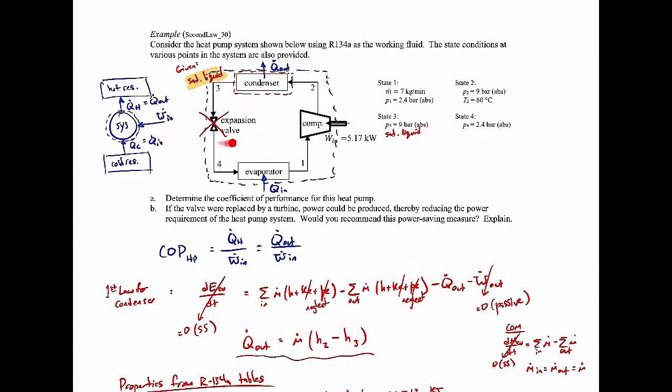That's in fact why these heat pump cycles and refrigeration cycles use expansion valves rather than a turbine, because you just don't get much out of the turbines. So you might as well go with something much simpler and save on other parts of your engineering consideration like cost, complexity, etc. Longevity. All right, we'll go ahead and end right there on that example.